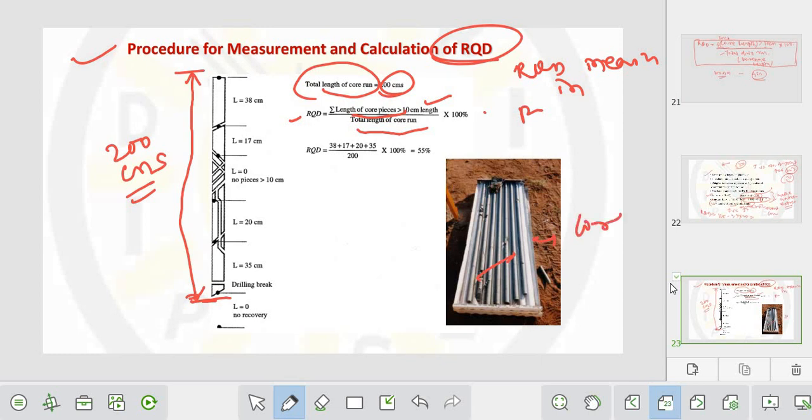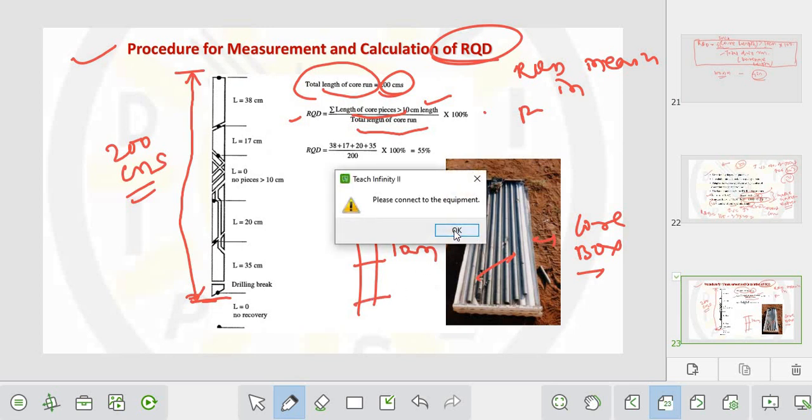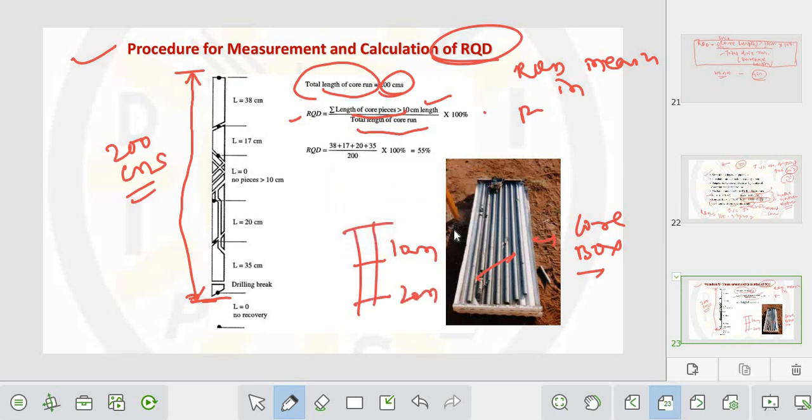This type of core sample you can get, ठीक है. ये core box होता है, ठीक है. In the core box, suppose ये 10 meter drill हुआ है, again the run will be from 20 meter. ये core box में आप जैसे मान लीजिए सैंपल उठाया है, डेप्थ वाइज इंक्रीजिंग ऑर्डर ऑफ डेप्थ पे आप सजाओगे all those cylindrical cores. Okay, so this is the core box in which the cylindrical core sample is normally kept, ठीक है. So the core drilling is up to 200 centimeter, ठीक है.